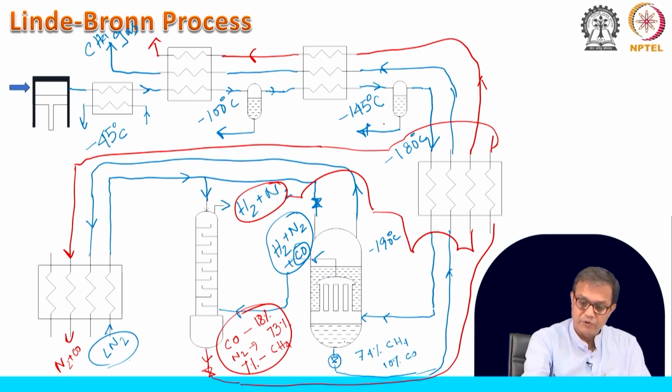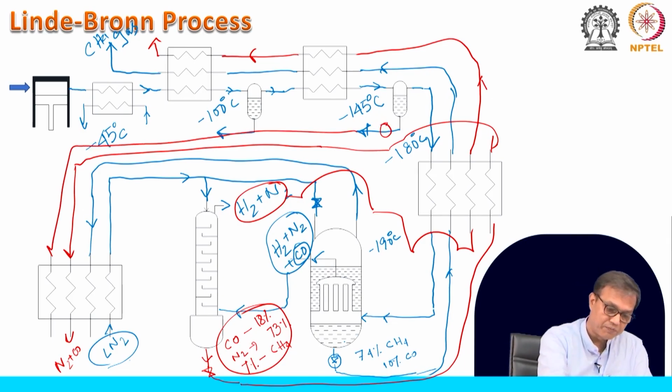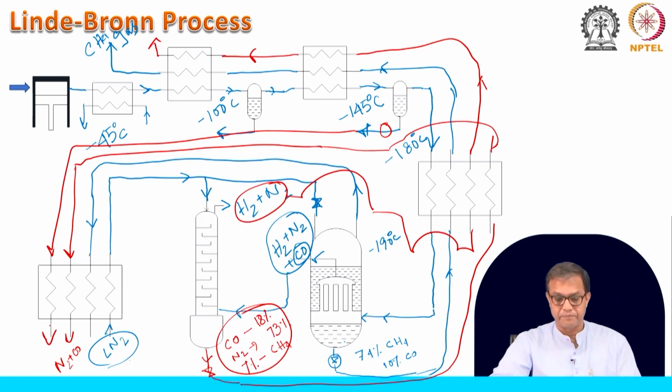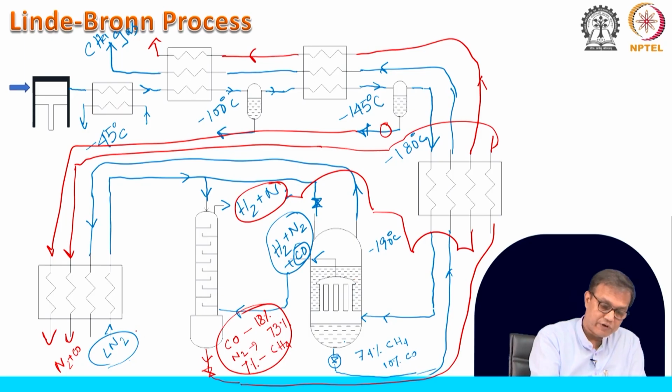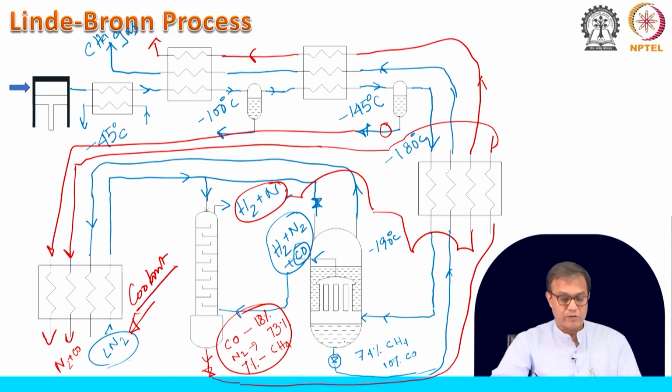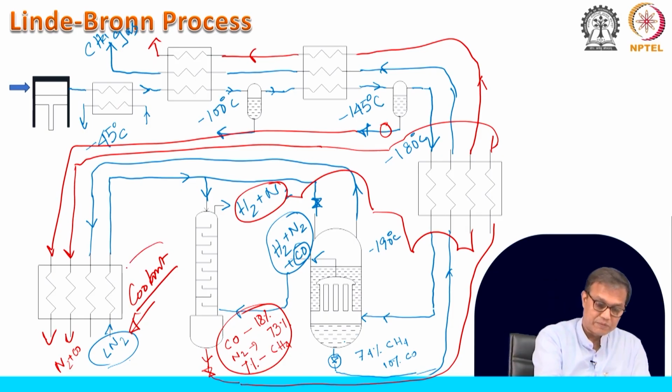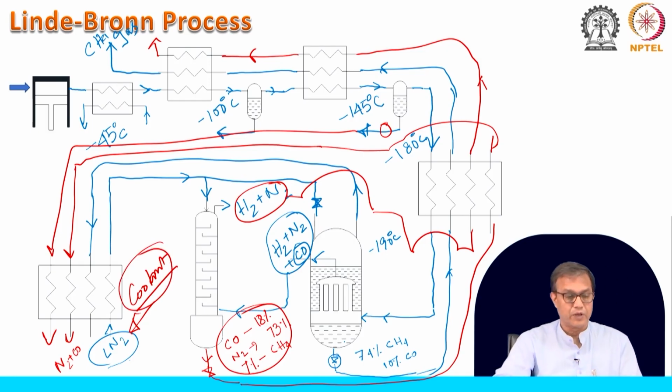There is another stream. We have produced some kind of ethylene, and this ethylene will be finally pushed through this 4 stream heat exchanger. So, we have a couple of heat exchangers. Along with that, we have this condenser evaporator and a CO scrubber, and most importantly, we have this coolant liquid nitrogen. In the Linde process, that has to be supplied along with the coke oven gas.